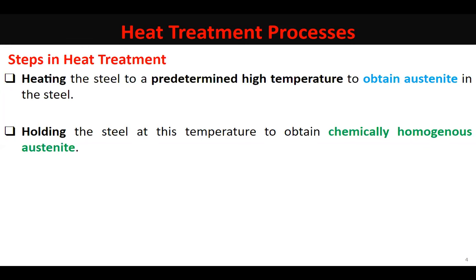So the process stops, and as the process stops, you say that whatsoever austenite was to get formed, it has got formed. But the point is that when you have completed the heating to the heat treatment temperature, austenite though has got formed, but there is austenite that gets formed in regions where originally ferrite was there, and austenite that gets formed in regions where originally cementite was there. I'm talking about the pearlitic structure, because it's the pearlitic structure which is getting transformed to austenite.